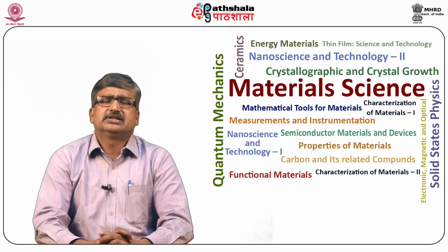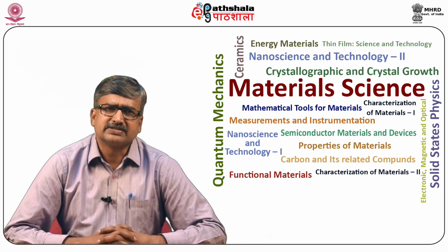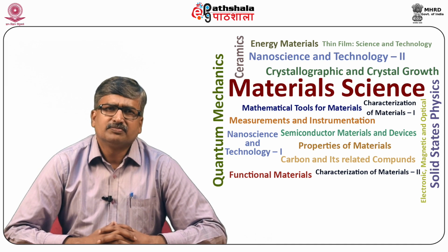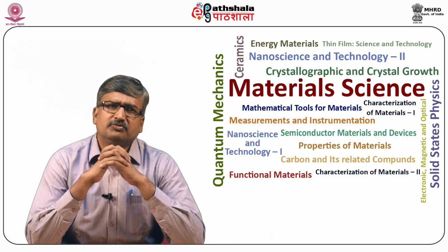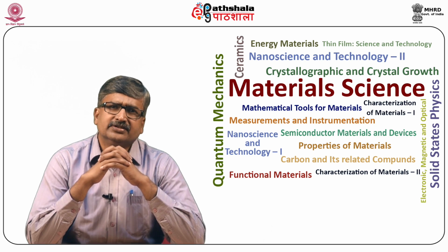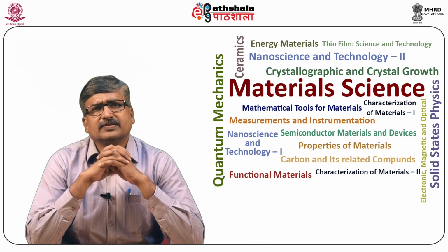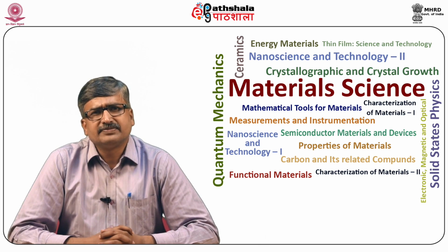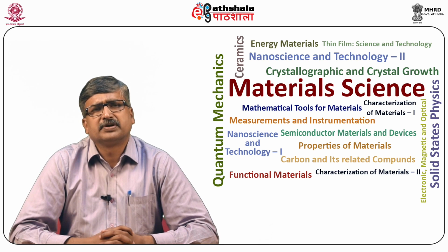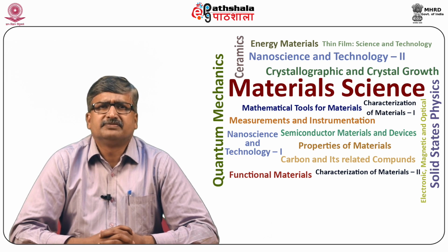So students, let us now summarize what we have learned in this module. CNT possesses several unique properties such as high Young's modulus, around 10^3 gigapascal, excellent electrical conductivity, around 10^6 Siemens per centimeter, and high charge mobility, which is of the order of 10^5 centimeter square per volt second. CNT provides high specific surface area and ease in functionalization for biosensing application.